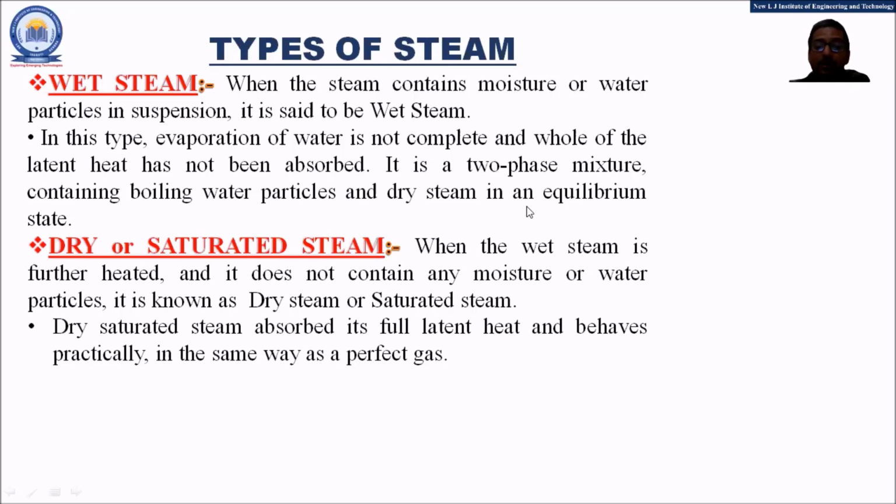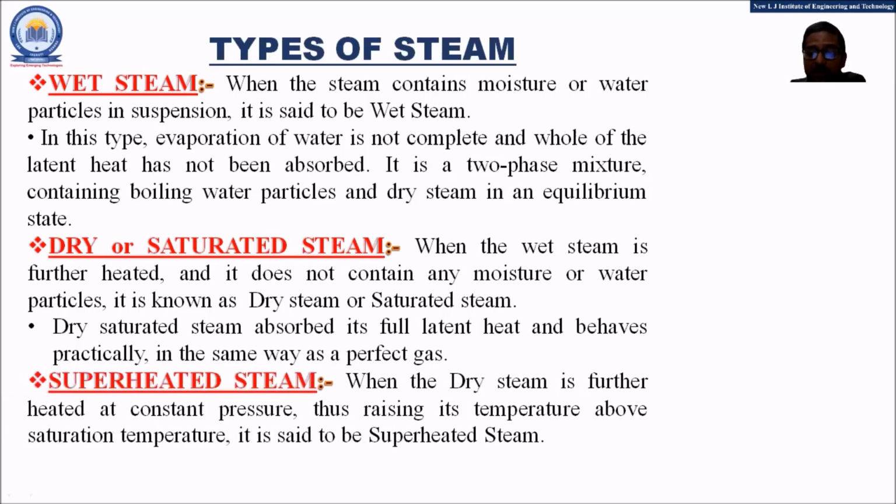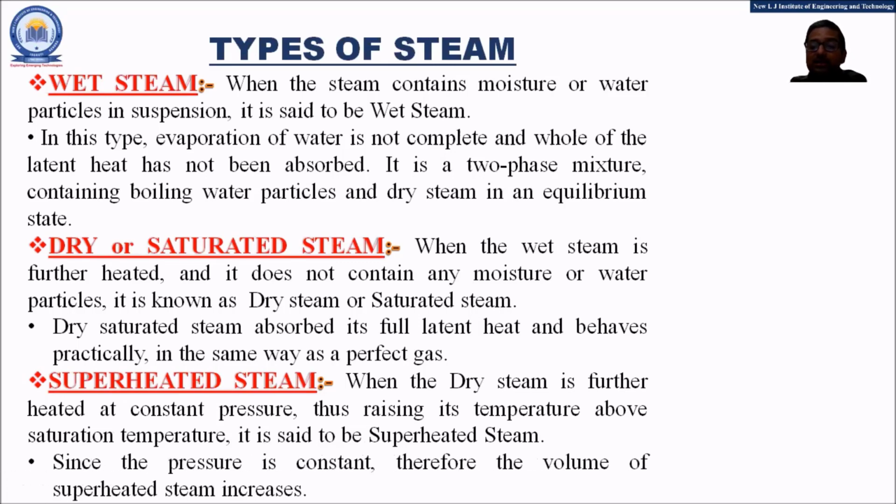Now let us proceed further and understand the third most important type of the steam, that is the superheated steam. As already discussed, when the dry steam is further heated at constant pressure conditions, thus raising its temperature above the saturation temperature, a new steam is developed which is having the maximum energy, and this steam is known as the superheated steam.